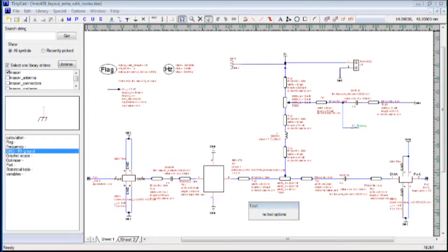Terminal 2 is 0, and that means it's not part of the simulation. Don't map it to an S-parameter port. Terminal 3, this 3rd number, gets mapped to port 2 of our touchstone file, and terminal 4 is also zeroed out, so it's not part of our simulation. It doesn't get mapped. So here we can take a 4-terminal device and map it to a 2-port S-parameter model.